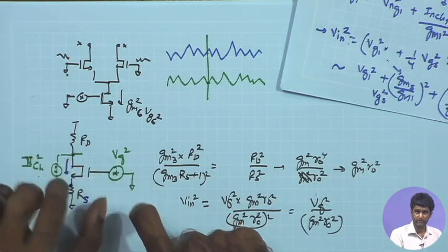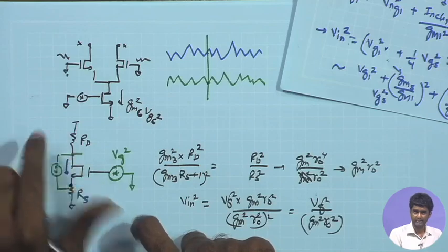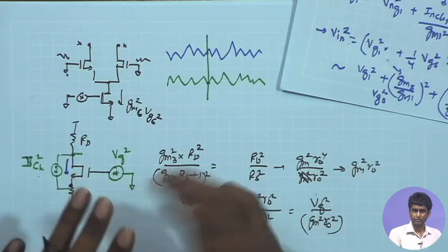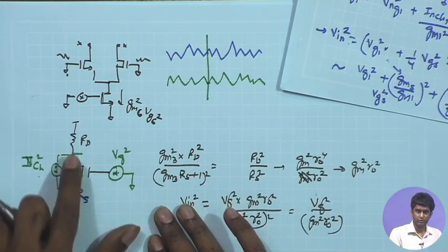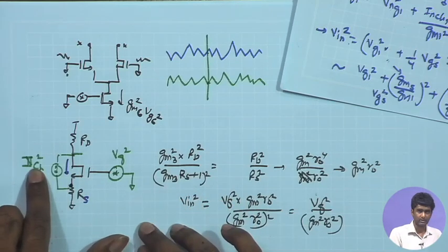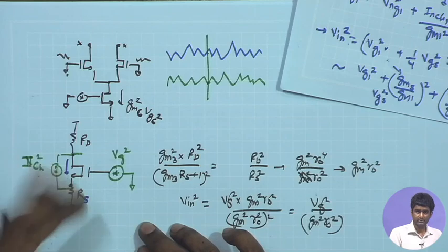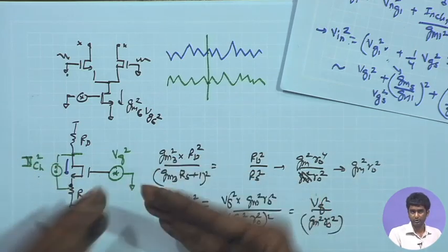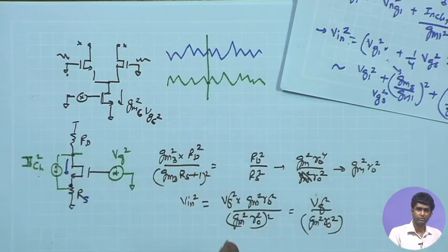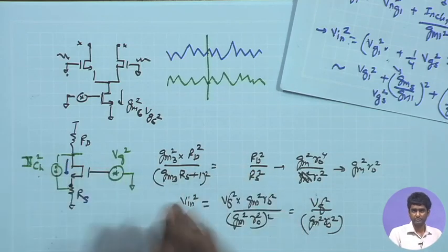So we are having a kind of negative path that is cancelling out any increase. This negative feedback is going to suppress the effect of I channel in this case. The same thing is true for VG also. That can also be explained with the help of this negative feedback. So ultimately, when we are talking about a source degenerated common source amplifier, that negative feedback action is present.